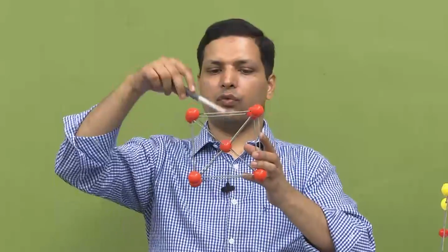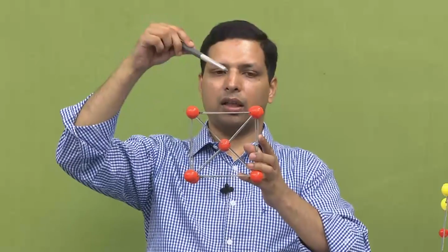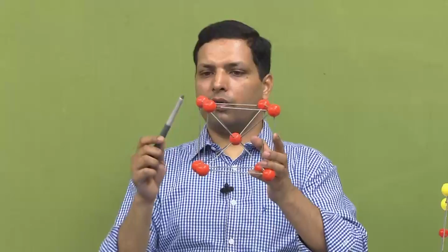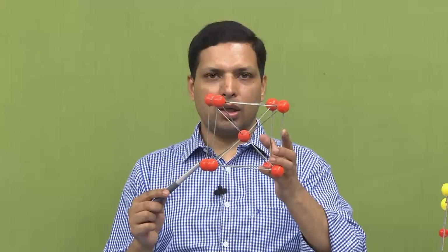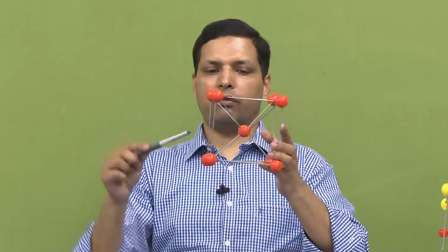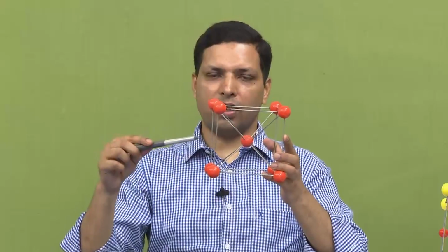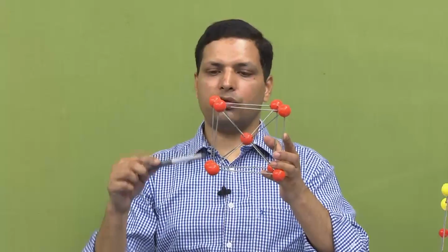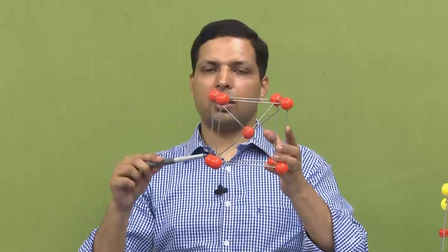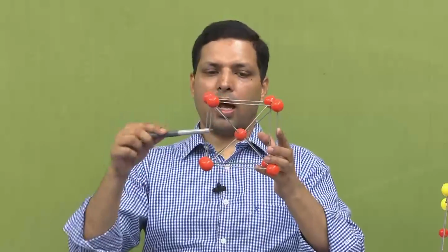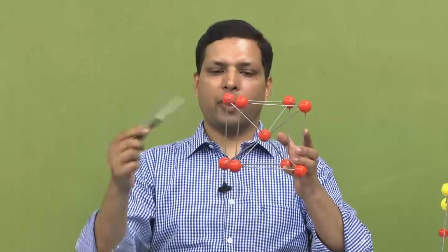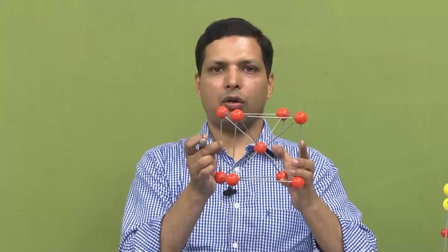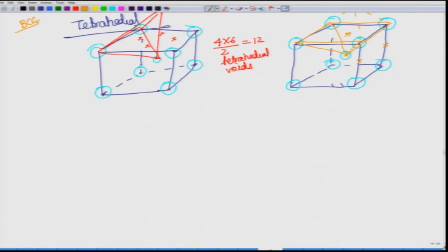So, now what you would see is we were talking about 2 atoms, one above the other, and a plane of atoms. Now, if you look over here, a similar kind of structure you have over here. So, this is as good as a body centered atom for some other cell. If we had the cell orientation shifted by half x, half y, half z, then this would have become the body center. So, this itself will become the center line, and this body center plus this body center plus this body center will form one plane, which means that at the edges of these also lies one octahedral void. So, we have octahedral voids also at the edges.